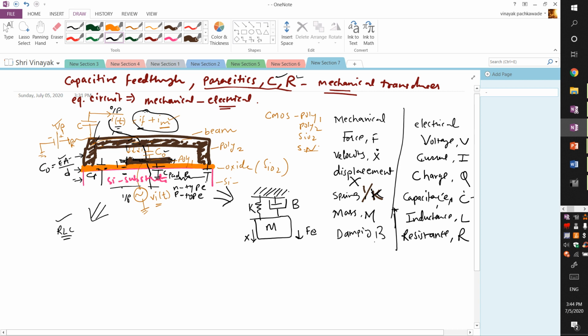So how do we derive this now? So now we have a mechanical transducer, mass, spring, and the damper, and it can be represented by a simple resistance R, which is a damping associated with this structure over here, and then we have the proof mass, which is the vibrating beam, indicated by L, and then we have this capacitance which is a reciprocal of this spring. Okay, so 1 over K. So that is an equivalent circuit, but now we have to apply the force.